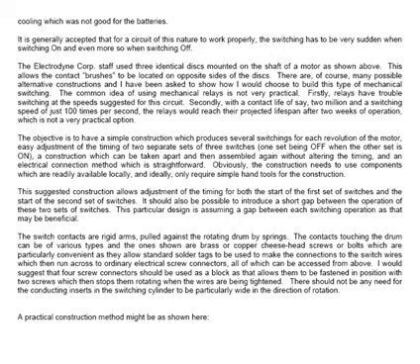The contacts touching the drum can be of various types, and the ones shown are brass or copper cheesehead screws or bolts, which are particularly convenient, as they allow standard solder tags to be used to make the electrical connections to the switch wires, which then run across to ordinary electrical screw connectors, all of which can be accessed from above.